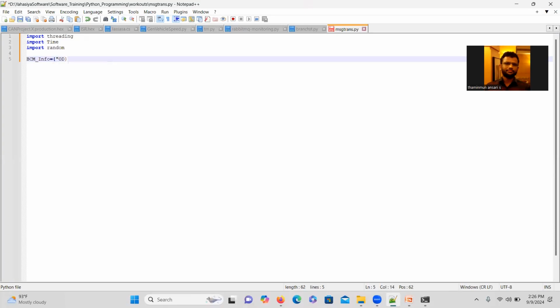The ID of the CAN packet as per the requirement is 123, and then channel, this is the first channel. Then we have DLC. It is only one because we are going to have only 1 byte in that packet. In that 1 byte only we are going to encode the vehicle speed.